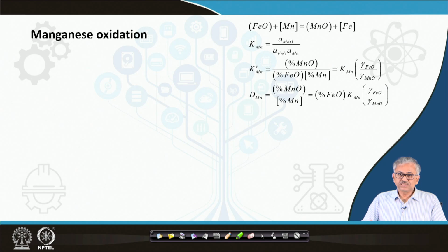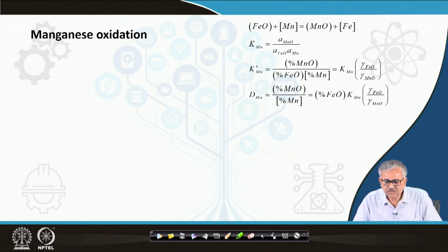If the slag is acidic, then MnO can be kept in, because it can form compounds and be retained in the slag. But if it is a basic slag, retaining MnO is very difficult. So this is the uniqueness of this impurity in liquid iron, that on oxidation forms a basic oxide. All other oxides are acidic oxides.